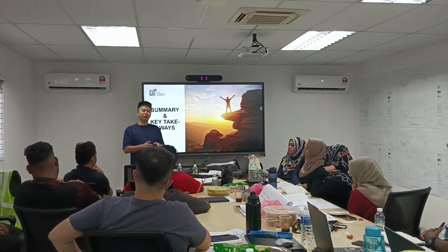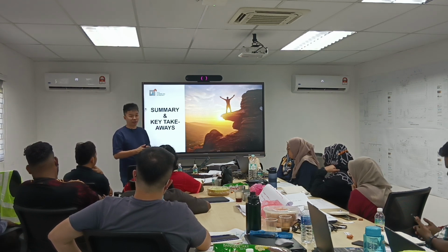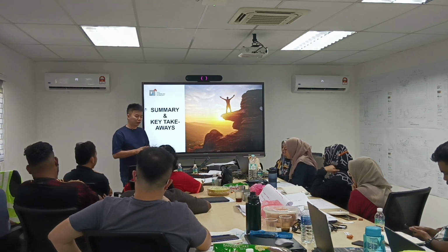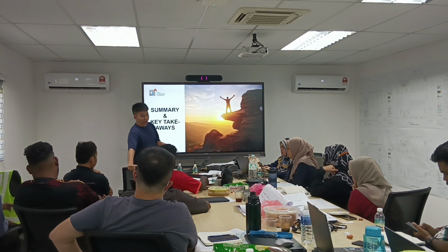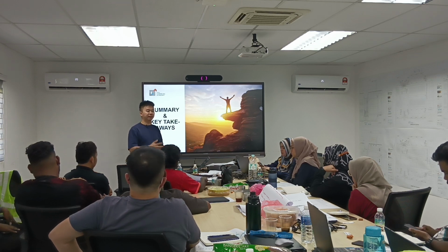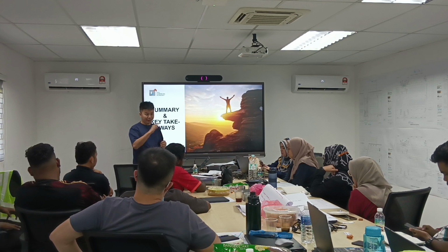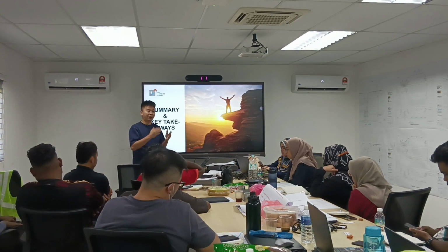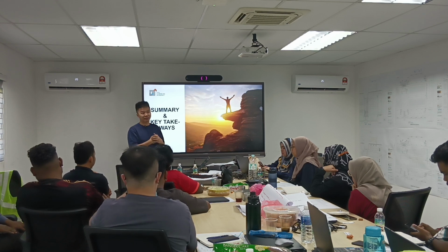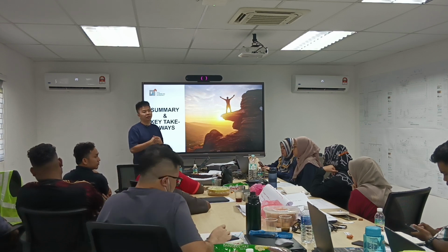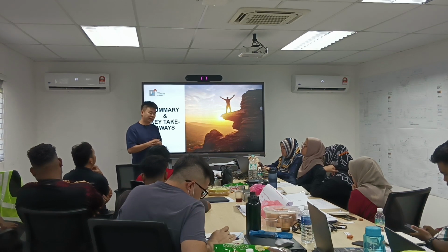Let's say we confirm the column is not off, and indeed the equipment position is off by 50 mm. Okay, no problem. Go back to our PQP. What is the tolerance we allow? 50? So if within 50, there's no reason the consultant will say he doesn't want to sign, because everything is already well defined in the PQP. But what if the PQP doesn't define? Let's say in your case, I suspect the PQP doesn't define. So let's say it's more than tolerance.